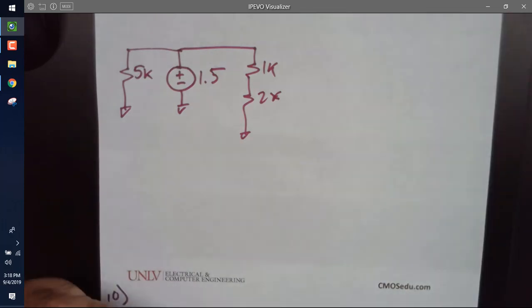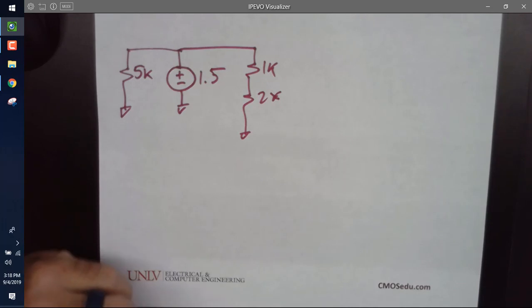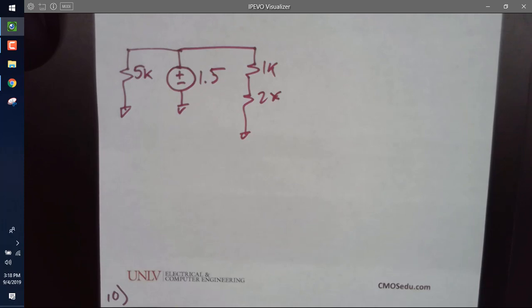Okay, so the reason I want you to know how to do this is if you get a job in circuits or doing chip design or whatever, and you don't know what the future brings, and you know what's important, being employed and making money. Okay, so when you get a job and you're using the tools, you need to know how they operate. And they don't talk to each other magically. They use like a text file, like I'm about to show you. When you have a schematic, it generates a text file and sends it to the simulator. They're not actually the same program.